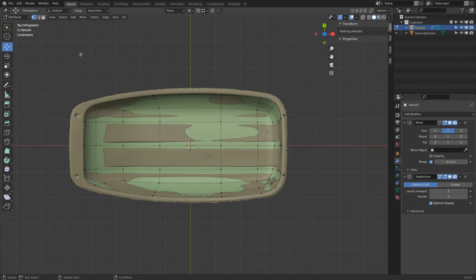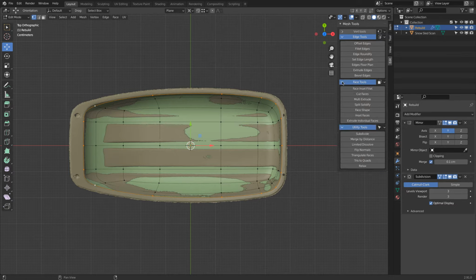Let's close this. We will Alt click on this edge, then we go to Edit, and we have here various commands like vertex chamfer, vertex extrude, or edge offset, edge fillet. Now offset, that's what we want. Some more utilities. So it's actually a good set of commands we use a lot.